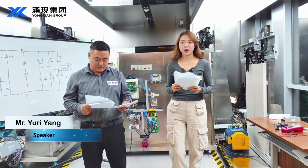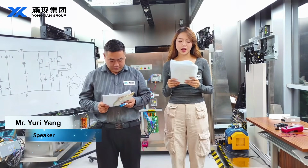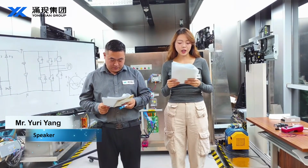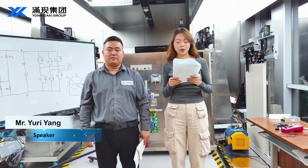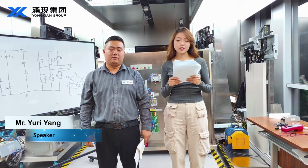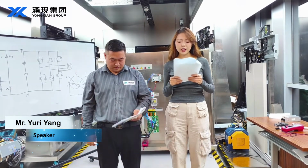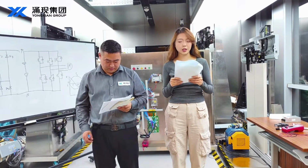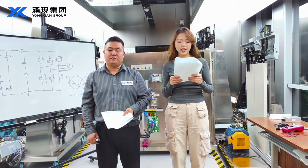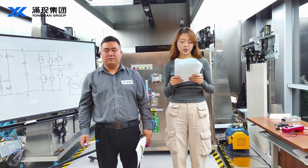Okay, now let's get into the first part, the working principle of the inverter main circuit. Inverter drive is a controller that regulates motor operation. It converts a fixed frequency alternating current power supply, 50 Hz in China, into an alternating current power supply with adjustable frequency and voltage, thereby controlling the motor rotational speed.